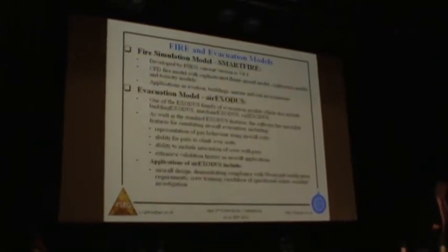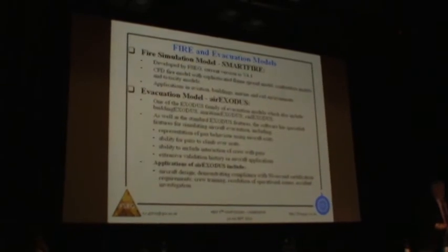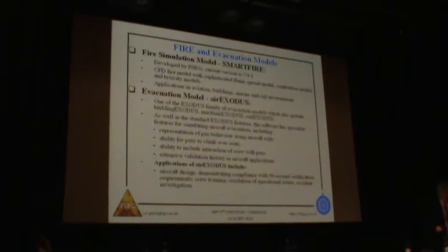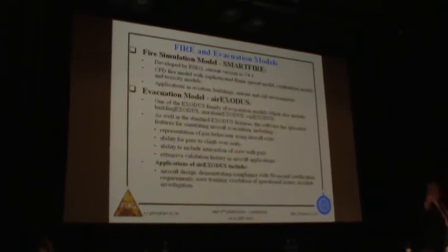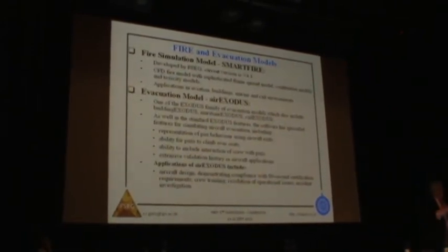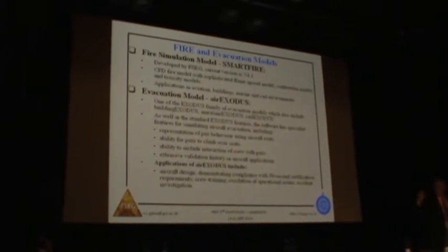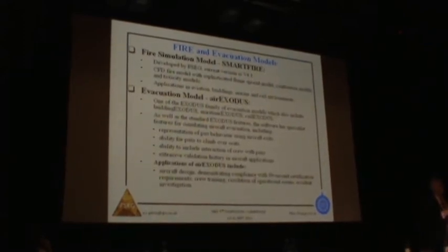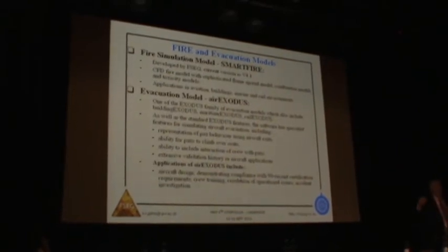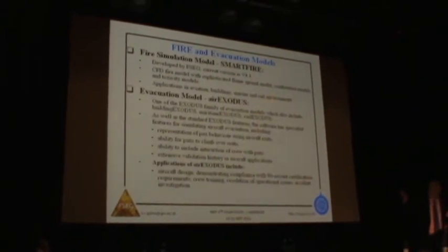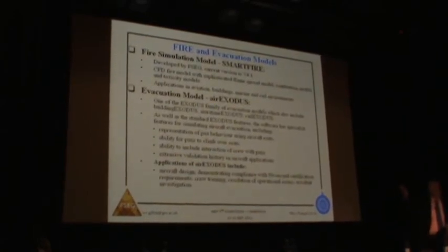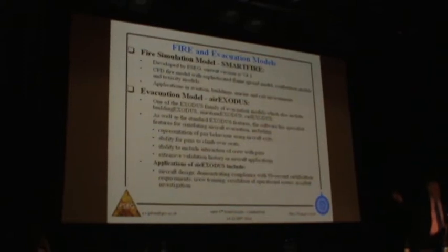So what we're going to use is the SMARTFIRE software, the CFD software, to simulate this fire, and we're going to use the airEXODUS software to simulate the evacuation. We couple the two and bring them together, and we transfer the fire data into the evacuation simulation software, and we look at the impact of the heat, smoke and toxic gases on the survivability of the passengers. This is the first software that was able to do this, linking of fire and evacuation together in this detailed CFD analysis and detailed evacuation analysis.